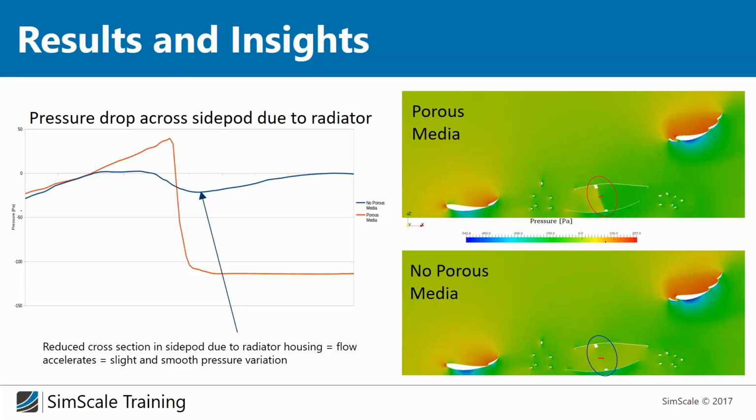The one effect is the massive pressure drop you have in this radiator, which means it increases a little bit the back pressure in front of the duct. And if you compare it, one result is also that the pressure decreases a little bit behind the radiator, and therefore also the influence on the rest of the car.